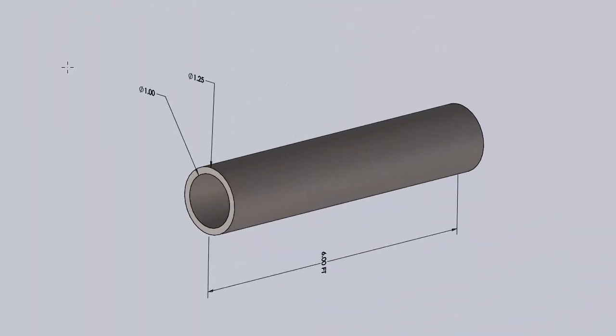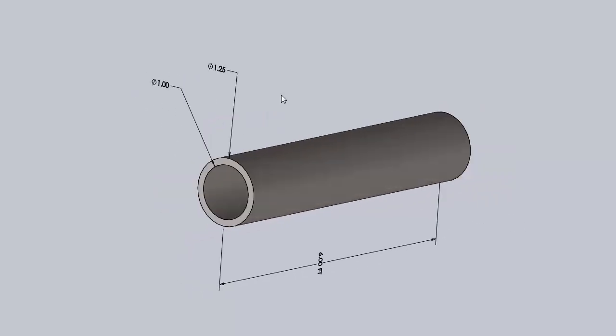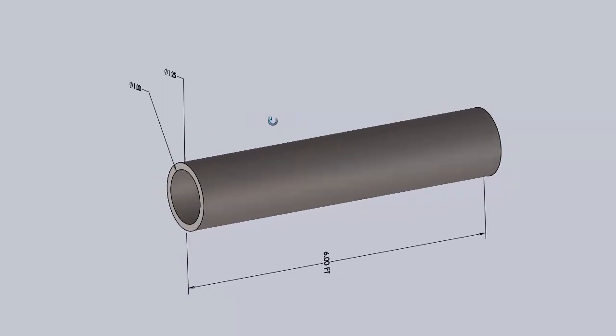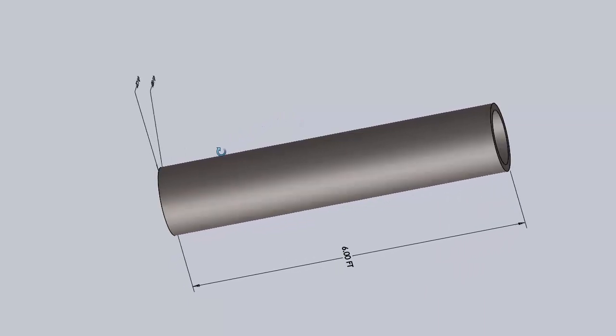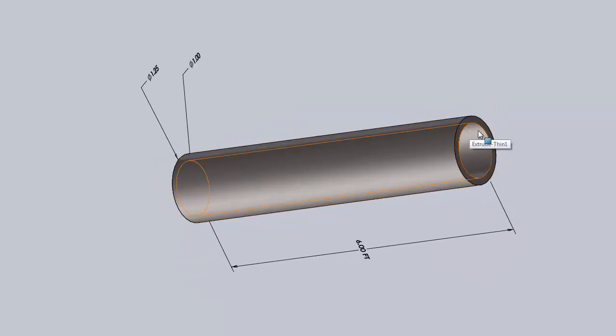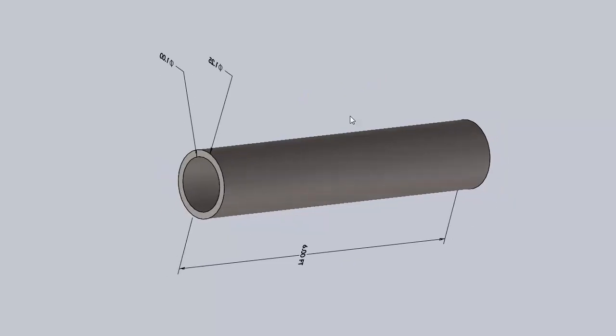So if we go to a diagram of a simple circular tube, we can assume that the tube is being twisted. There's a torque on this side and an opposing torque on this side. This will induce a shear stress and will also cause it to have a deflection in a twisting fashion, so it's an actual angle.